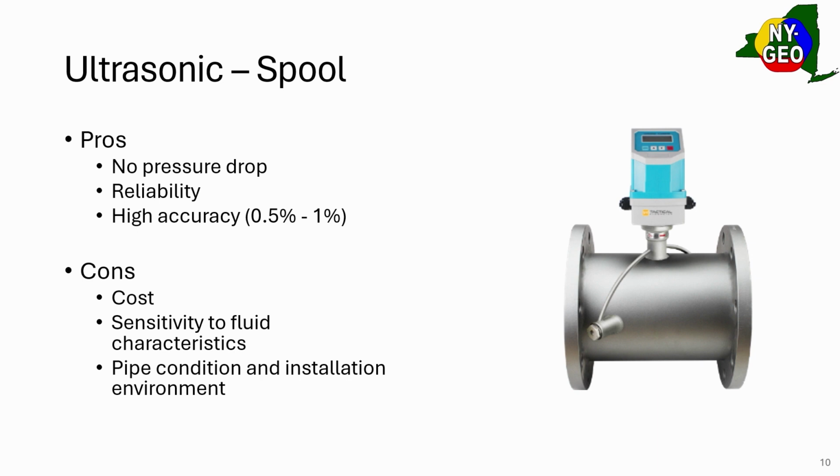Thank you. Andrew Wilcox from Undercity Energy in Toronto. Just a couple of comments on some of those metering technologies, less of a question. The clamp-on ultrasonic meters: I'm not sure that any clamp-on meters are actually approved for billing purposes under Measurement Canada, so that's one thing. Also, they're great tools for validation of flow rates or BTU measurement, especially in industrial applications.